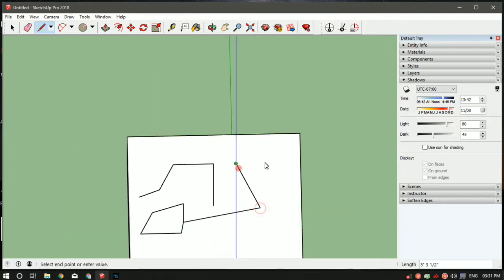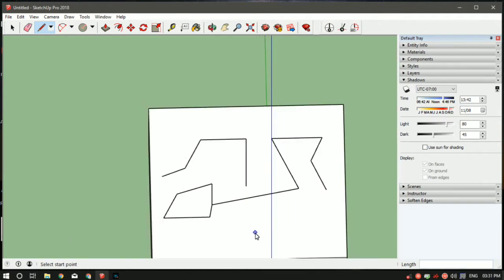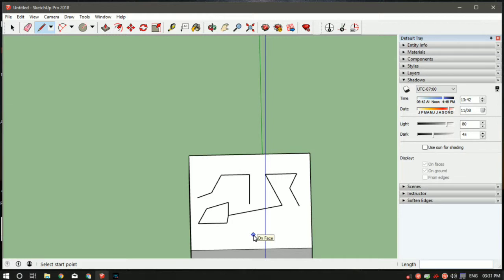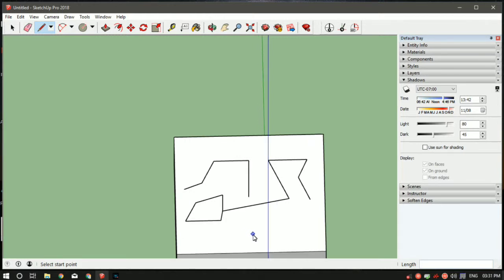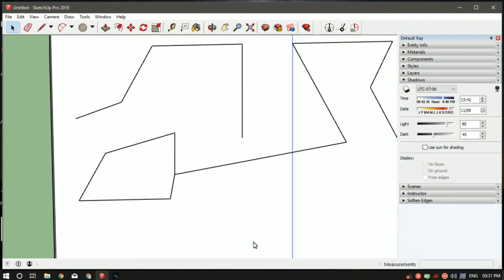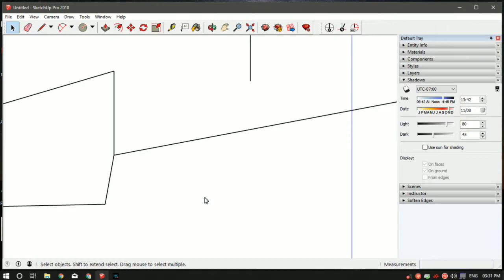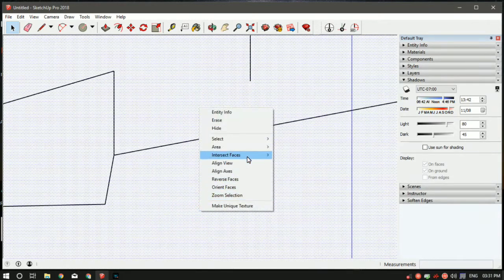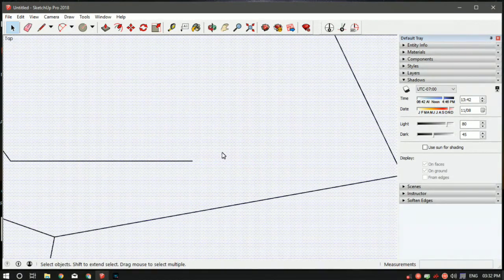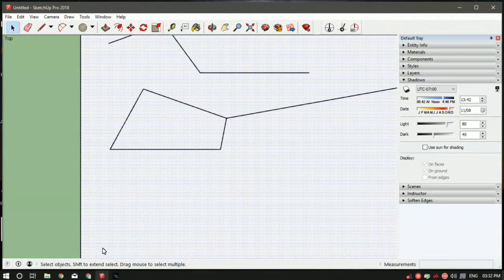Let's say this is basically making some random lines, but let's say you want to make a line of 10 mm height or 10 mm length or 10 meter length, 10 feet length, 10 centimeter length. How can you do that? It is pretty easy. Let me come out of the command by pressing the spacebar. Again, right click, align view, and let me zoom in over here.